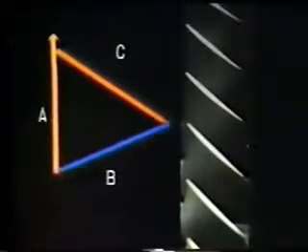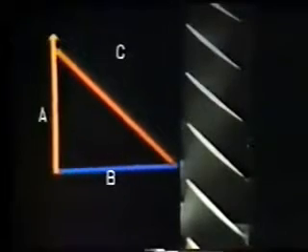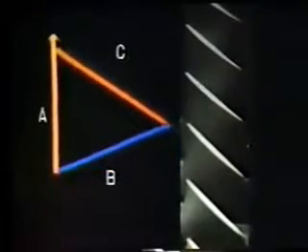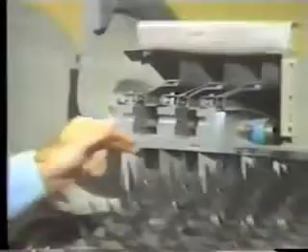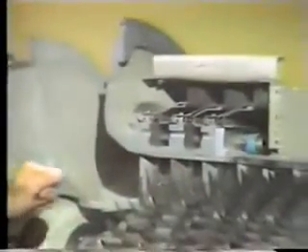The first stage rotor has a speed and direction shown by vector A. The inlet guide vane can direct incoming air at a new angle. Vector B shows the new angle. Its length is unchanged from before because the velocity of incoming air remains high. You see both the relative angle and velocity of incoming air are reduced, shown here by resulting vector C. By controlling the angle at which air enters the first three stages, a stall condition is avoided during the start cycle.